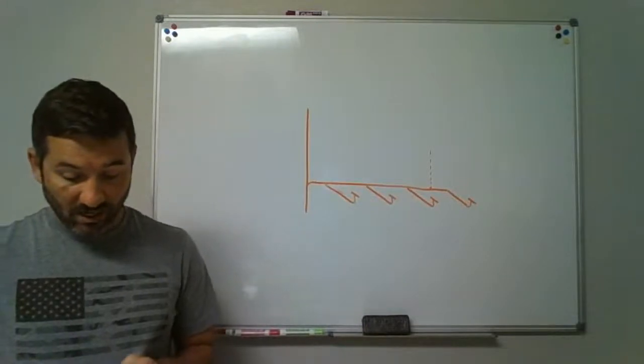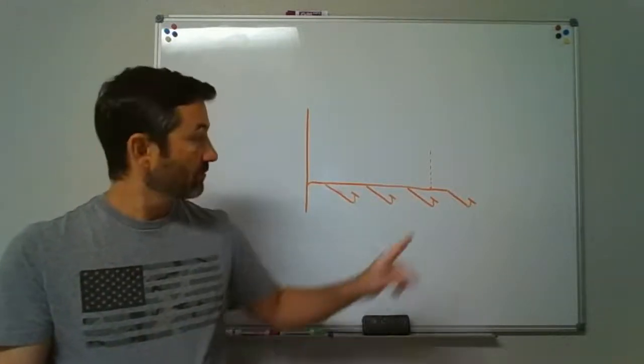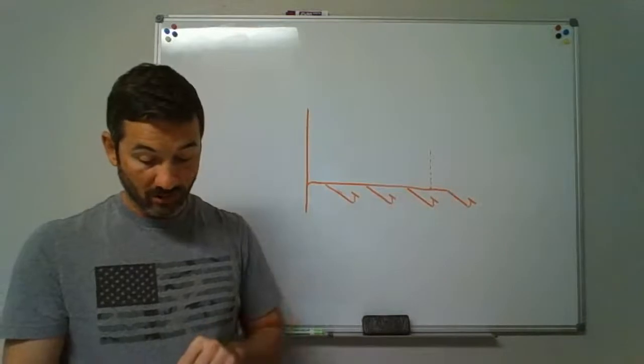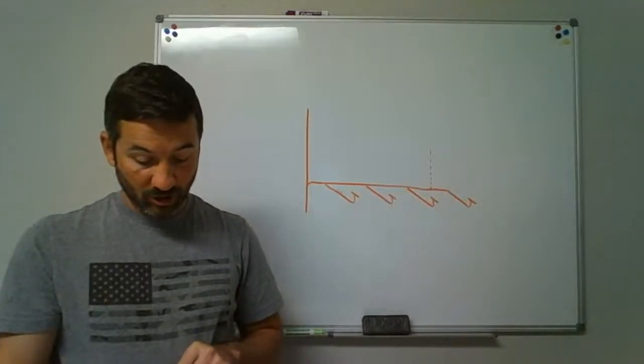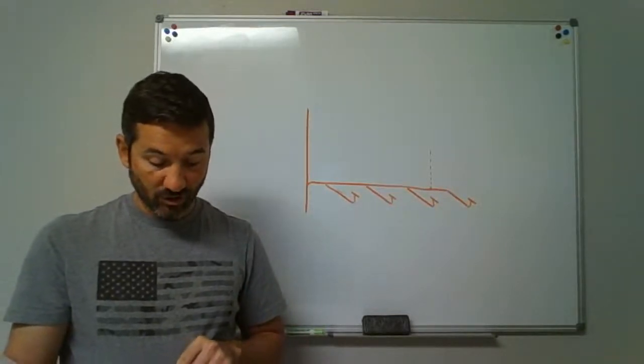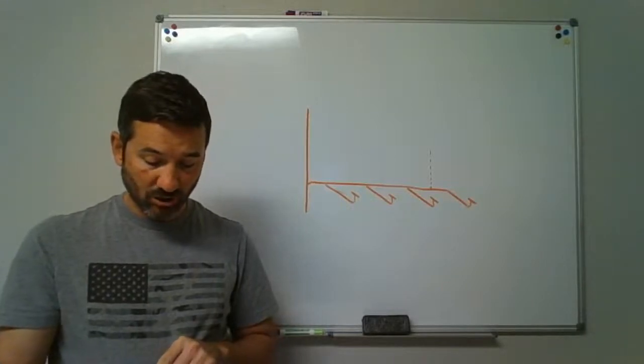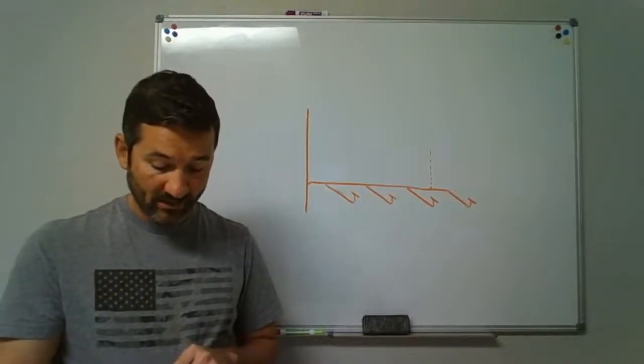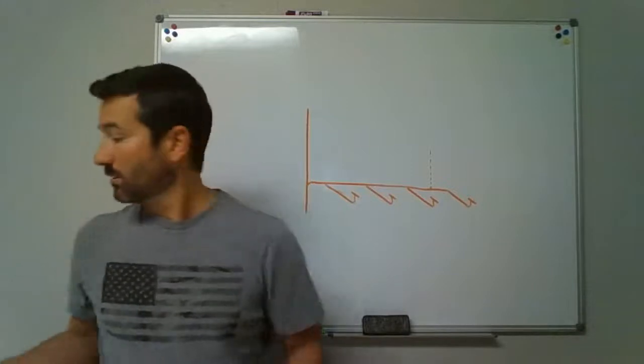The vent shall connect to the horizontal branch, right in here into the horizontal branch, and should be installed in accordance with Section 905. The circuit vent pipe shall not receive the discharge of any soil or waste. Okay.